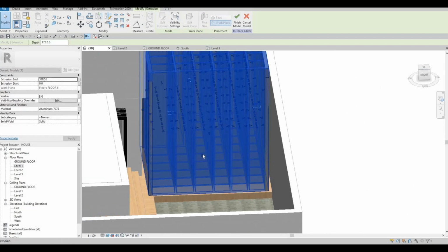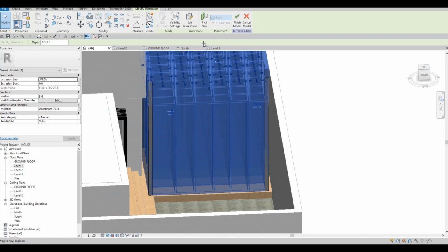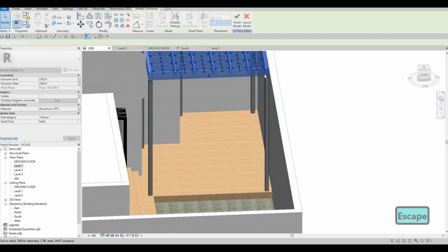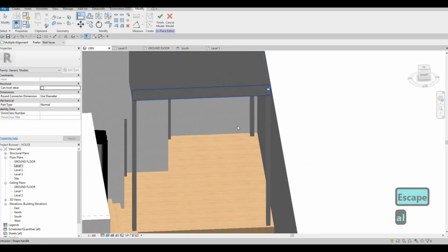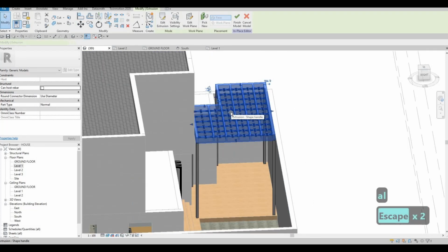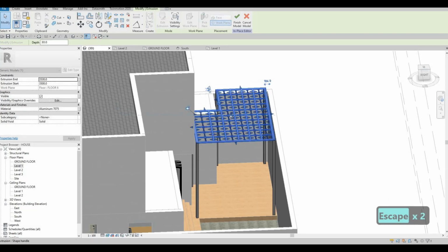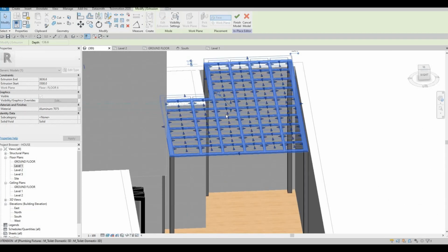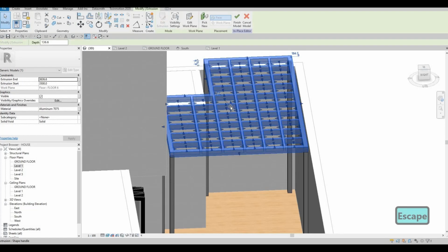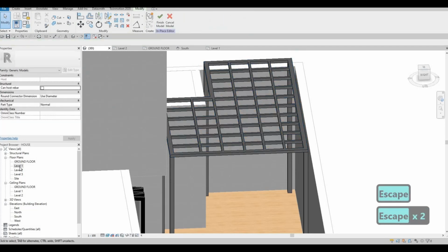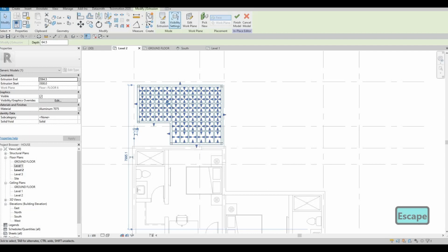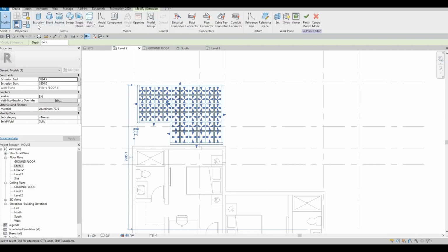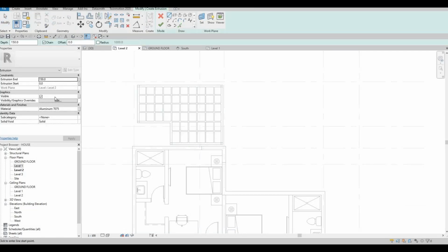I'm gonna go over first and then pull up the bottom part, and that one we're going to align from here, and then we could just decide the thickness of this one. There we go. And then what we need to do afterwards is just select this again. We're still here, so we just need to add an extrusion.